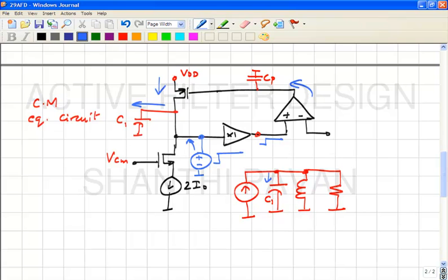Alright, which means that the output voltage, which basically means that all the current, if Cc wasn't there, all the instantaneous current at t equal to 0 is all flowing through the capacitor, and that makes sense, because if Cc wasn't around, then this loop looks like this. All the instantaneous current flows through C1. An inductor's current cannot be changed instantaneously, correct? So no current flows through the inductor, and it's all self-consistent.